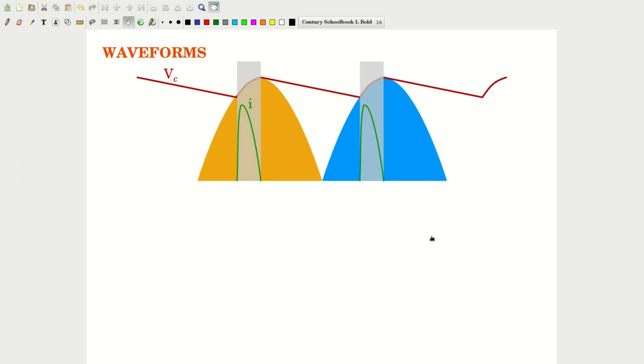Now let us look at the load current and the capacitor currents. The load current will follow the voltage at that node, the VC node. So that VC value divided by R will be the I naught, and it will have some ripple as seen here. We can approximate the average right through this as shown, and for practical purposes we can take this I naught as the current flowing through the output, ripple free, but be aware that there will be a small ripple.